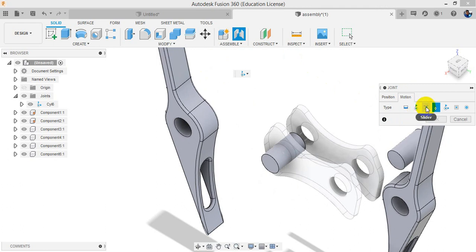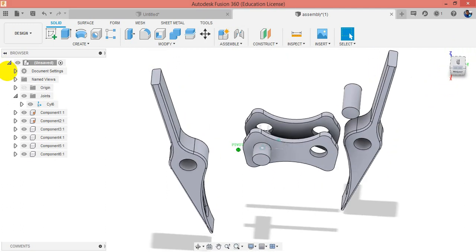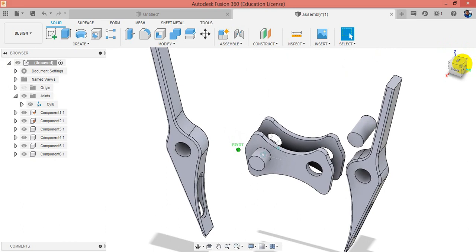So these three joints actually make things easier for you. You also have pin slot joints, which are very much special cases, planar joints, ball joints, and slider joints. Those are for advanced machines, and you can apply them at the intermediate stages. So I'm not going to show you those. You can apply these three joints and make your simple assemblies complete.